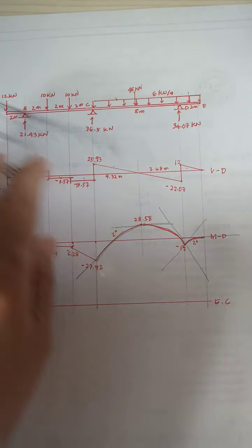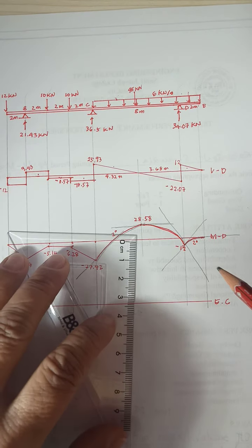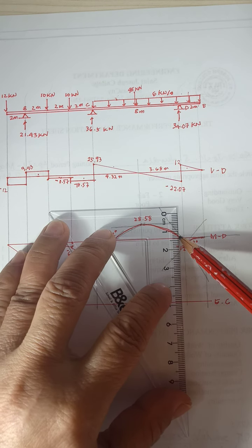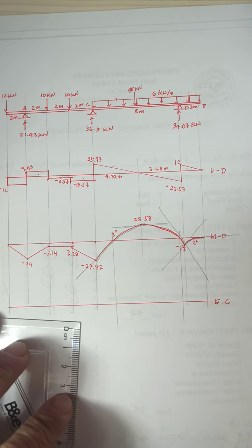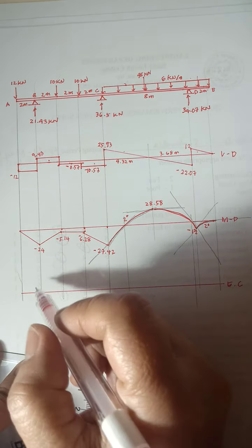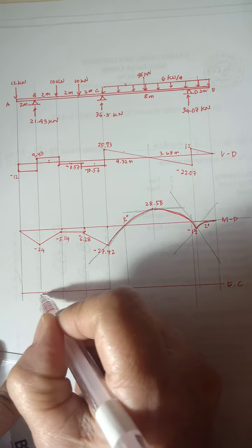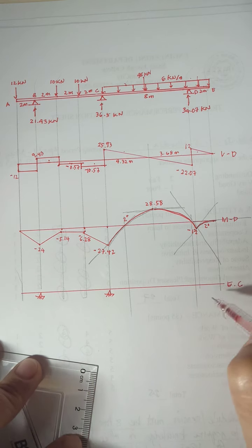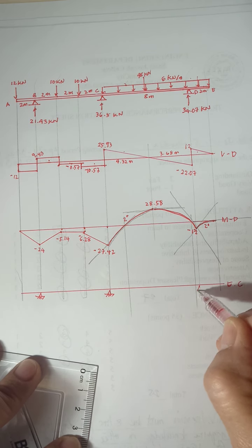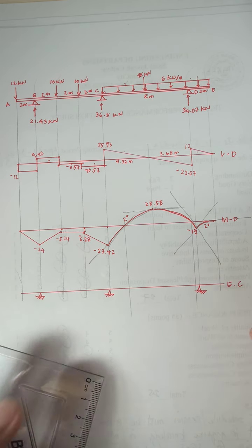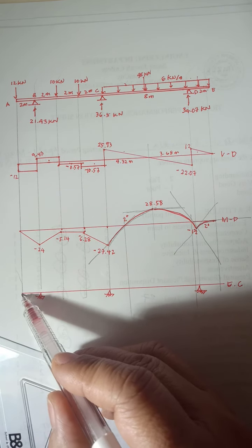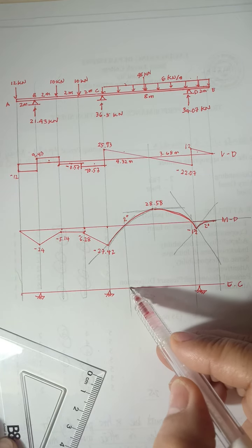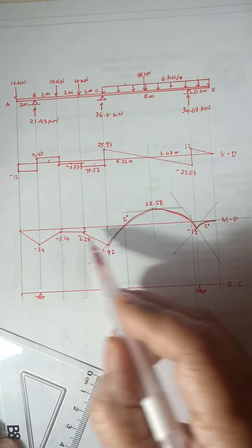Okay, so to draw the elastic curve, as discussed before, you have to project the 0 moment, because that is your points of inflection. Okay, so place the supports so that you will know that at that point there is no settlement or deflection, so your beam will not deflect. Okay, so from the left end up to this point, isn't your moment negative?